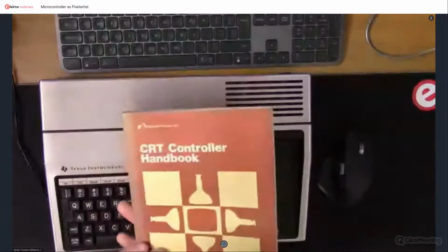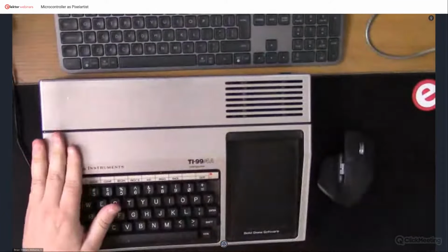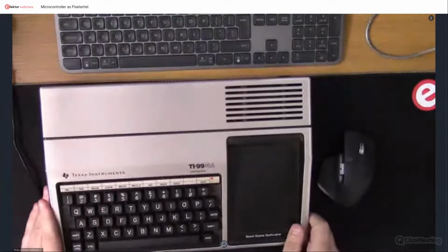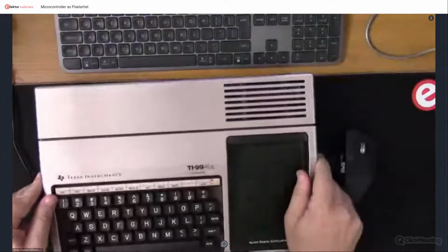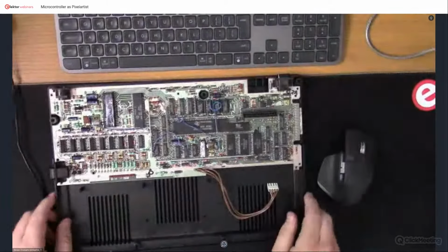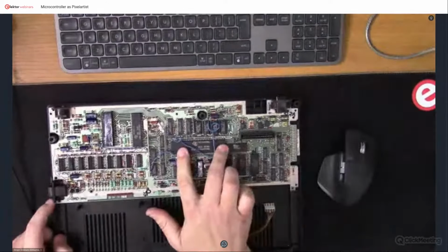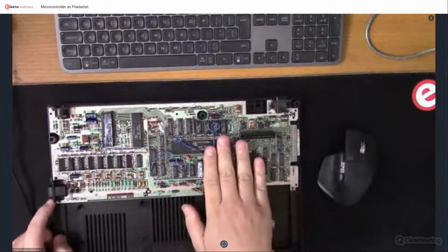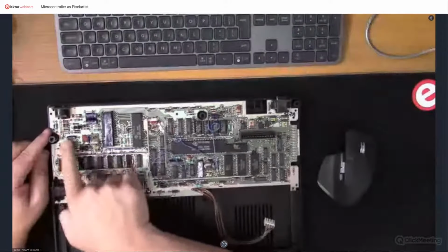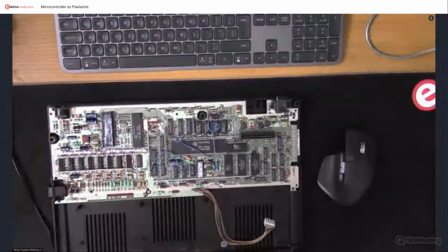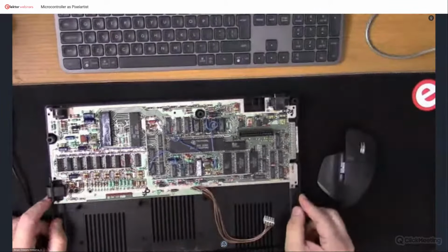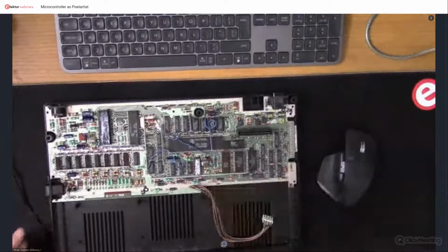And, you know, they had all kinds of hardware and books on them on how to generate the characters. And that's great, but this is a 42-year-old machine. We have since advanced to things like Arduino, but they don't have video output. If we take a look inside here, you can see this big baby here is the microprocessor. It has RAM and ROM connected, but this entire section here is analog video output, the video chip, and 16 kilobytes of RAM. So I'm thinking with an Arduino running at 16 megahertz and this thing only running at 3,